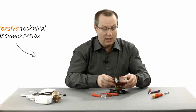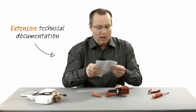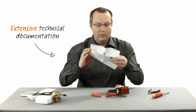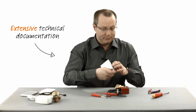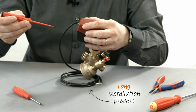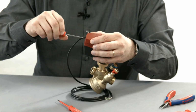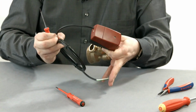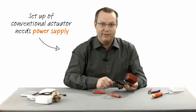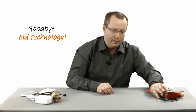One of the difficulties is to know which dip switch to turn, and for this you need to bring along with you some installation instructions that will document you on which switch to turn in order to obtain the function that you want to apply to the actuator. You need then to fix back the compartment to be finished, and obviously this configuration requires you to have the actuator connected to the power supply to be able to see the effect of your configuration. This way of doing is part of the past.